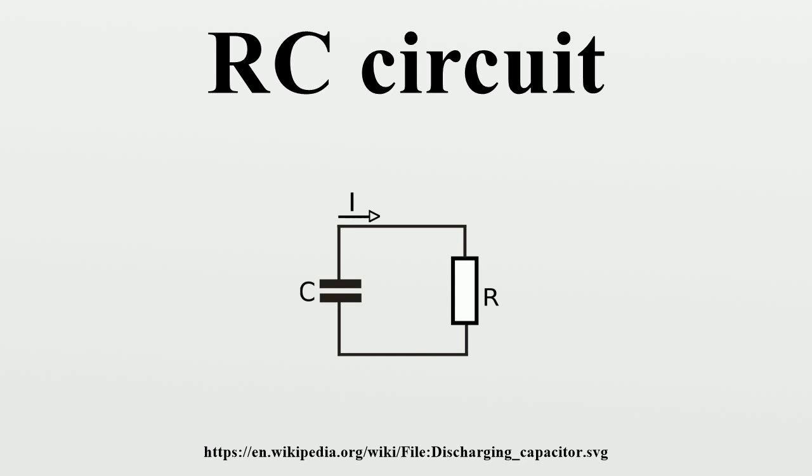So at DC, the capacitor voltage is in phase with the signal voltage while the resistor voltage leads it by 90 degrees. As frequency increases, the capacitor voltage comes to have a 90 degrees lag relative to the signal and the resistor voltage comes to be in phase with the signal.